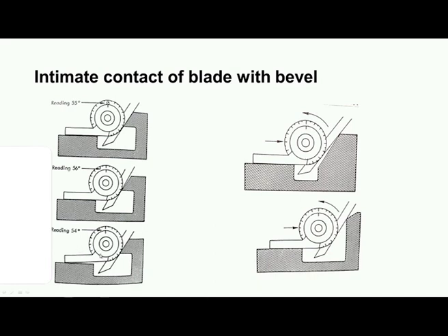So, sometimes the one blade, the sliding blade is in contact with the workpiece, but here fixed blade is not in contact. It is actually the protractor is climbing on the workpiece. So, there is no contact here. So, the angle shown is 54 degree, which is smaller than the actual angle.